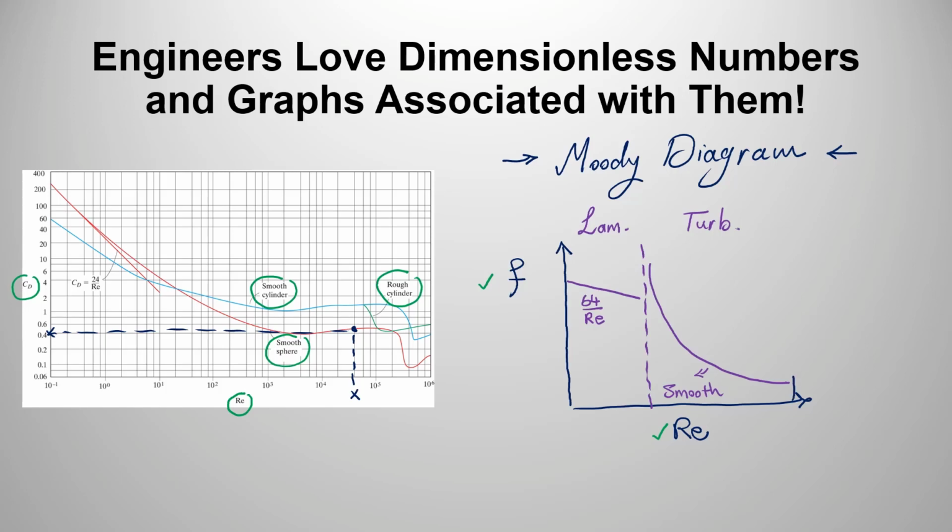It's pretty easy right now, you know, right? It was the second y-axis, and it was called k_s over D, or relative roughness. And k_s is the sand equivalent roughness, and D is the diameter. So the dimension for both of these is length over length, meaning that it's dimensionless. And they came up with different relative roughness, right? And different curves for different relative roughness over the range of different D's and different V's were developed.